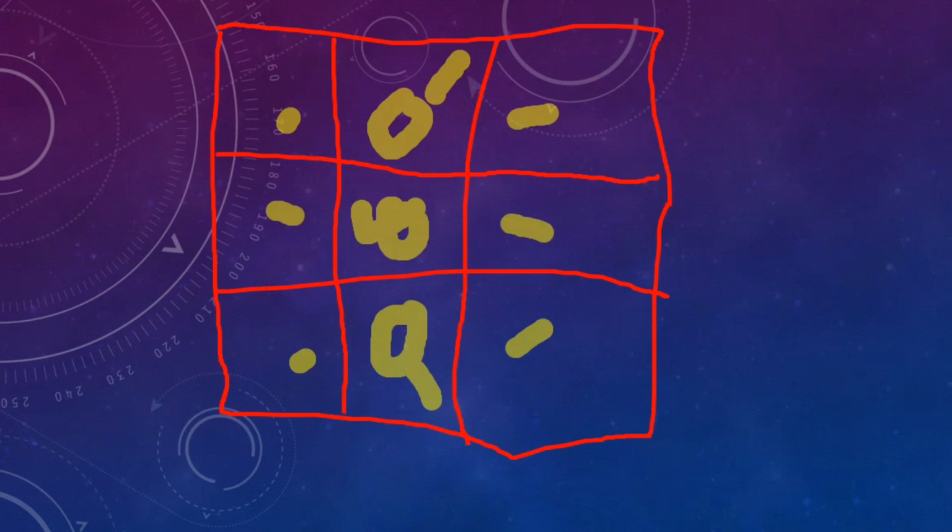As per the cooling load calculation, I need to provide 2 supply air diffusers. Matching that, I provide 2 return air diffusers. So I need to provide 4 diffusers in this room, 2 supply air diffusers and 2 return air diffusers. In this room, I don't have any option because the sprinkler is already there and the lighting is there. And the third important thing, I am going with the diffuser. So I cannot tell them that you have to move the lighting here, or you have to move the sprinkler here, so that I can make a proper minimum distance of 1 meter or 1.5 meter. So this is the practical thing.